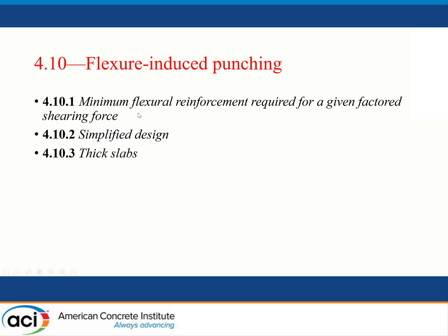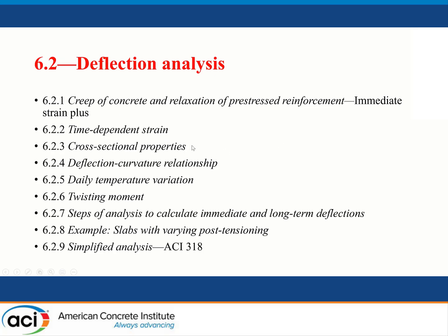And so this is one of the main additions to this guide, in addition to the expansion of the analysis methods. So minimum flexure reinforcement required for a given factored shearing force, simplified design, and considerations for thick slabs.